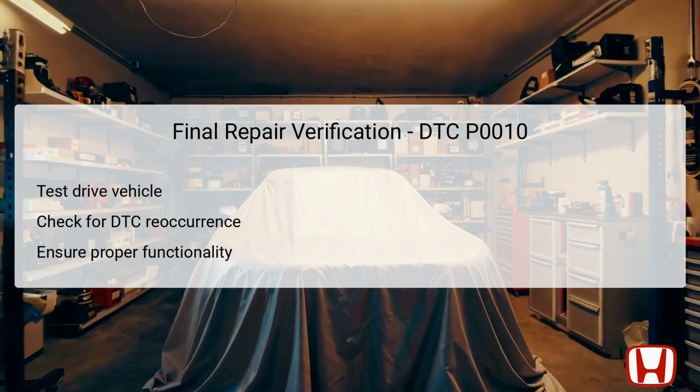After completing the necessary repairs and replacements related to DTC P0010, it's crucial to conduct a final verification to confirm that all changes have resolved the issue. A test drive should be performed under conditions like those previously recorded in the freeze frame data. During this test, monitor the vehicle's performance, including smooth acceleration and the absence of warning lights on the dashboard.